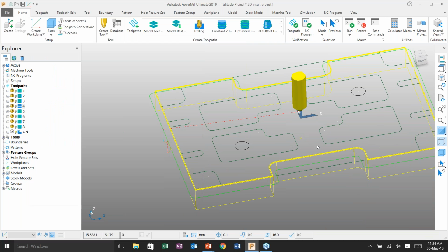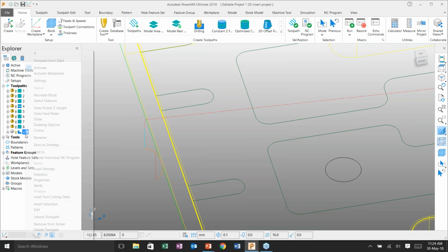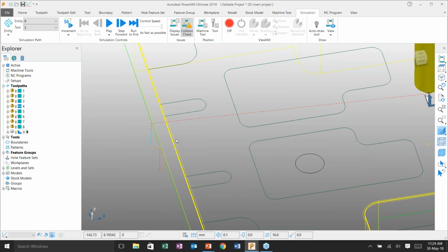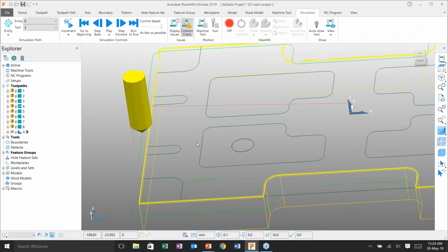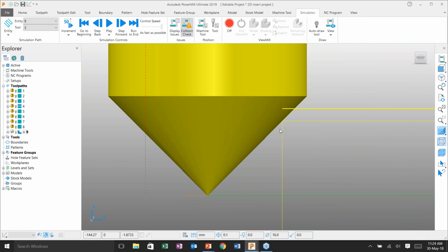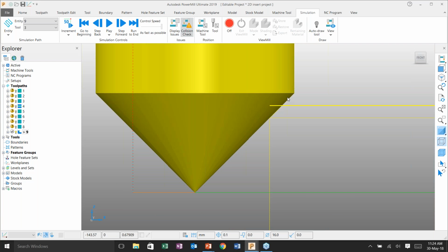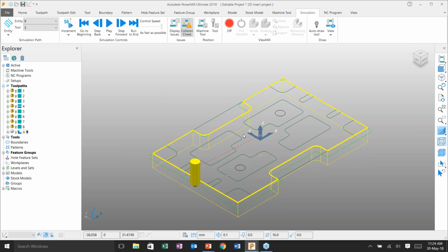It will come in this fashion. It smoothly enters here. I will show in a 2D simulation here. Just well plunge outside. If you come into the front face, you can notice that the chamfer is created in the toolpath here. Just move along. It's very fast to create this particular kind of chamfer toolpath if you are using the 2D machining option.